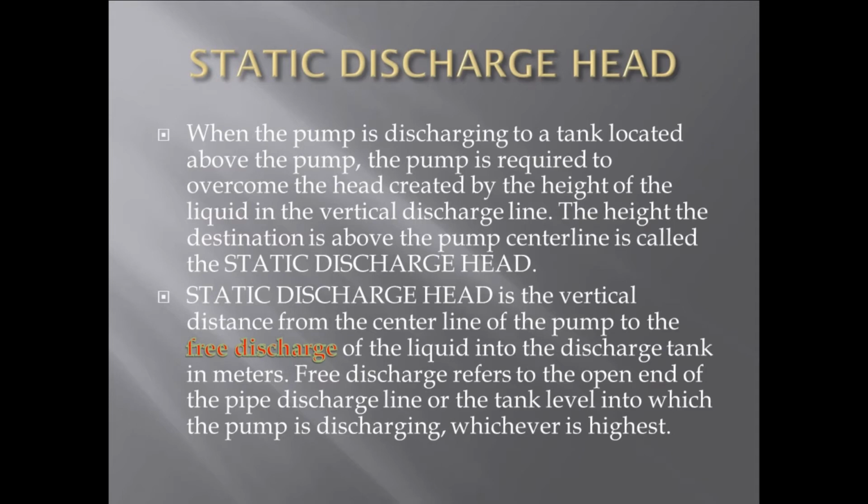Static discharge head. When the pump is discharging to a tank located above the pump, it is required to overcome the head created by the height of the liquid in the vertical discharge line. The height the destination is above the pump center line is called the static discharge head.